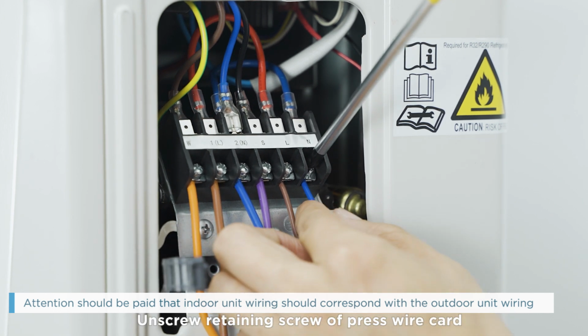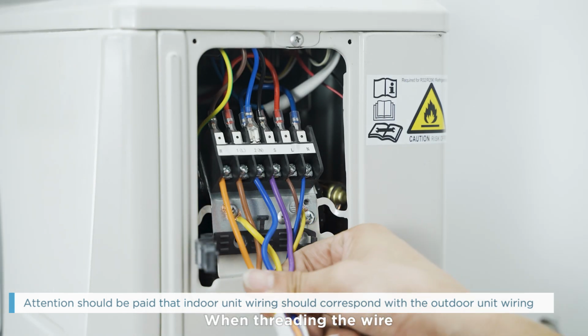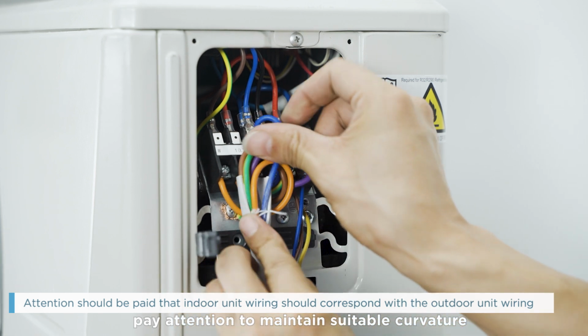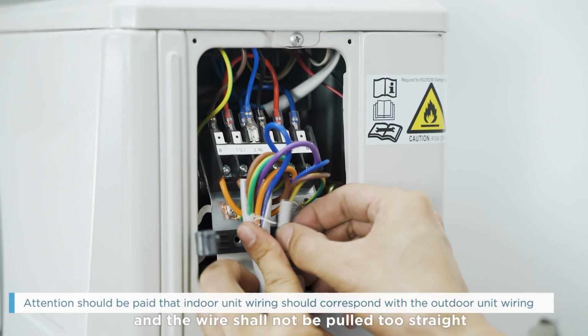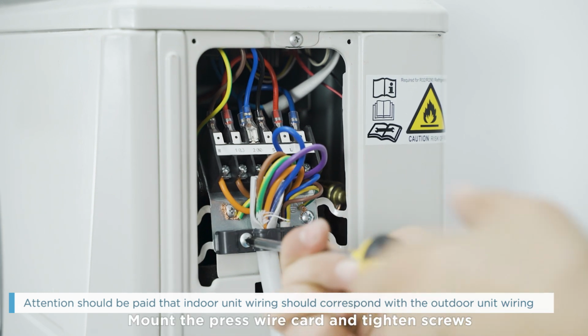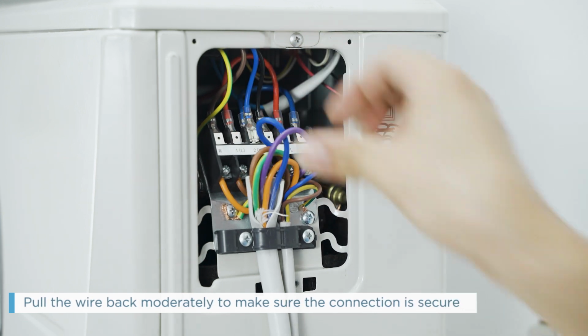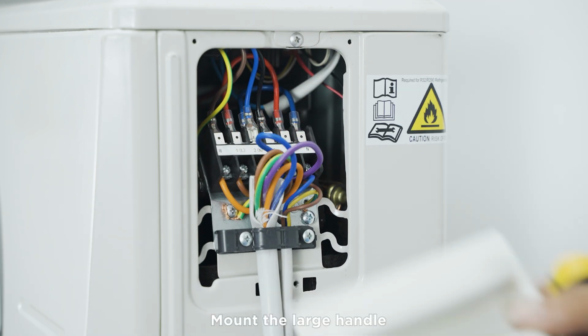Unscrew the retaining screw of the press wire card. Remove the press wire card. When threading the wire, pay attention to maintain suitable curvature, and the wire shall not be pulled too straight. Mount the press wire card and tighten the screws. Pull the wire back moderately to make sure the connection is secure. Mount the large handle.